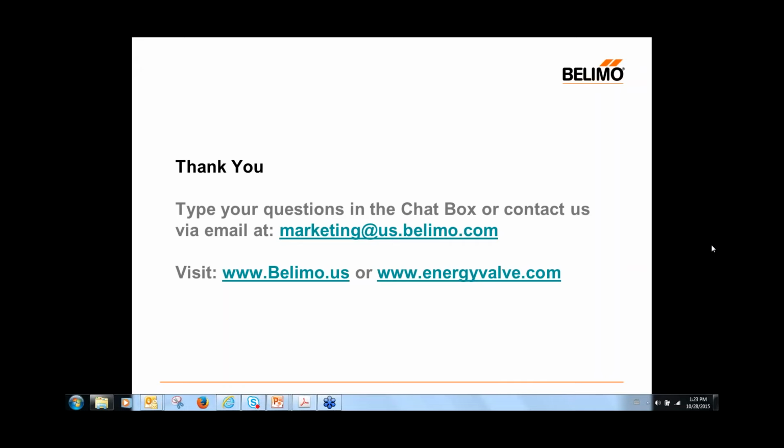Okay, next question. What are the 3 levels of access to the energy valve? Would that be for me? Yes, sorry. That would be guest, maintenance, and administrative. Okay. Next question. The delta T control still requires a 2-10 VDC signal to the actuator. That was a question. Does it require 2 to 10 volt DC signal? Yes, it does. Okay, great. Thank you.